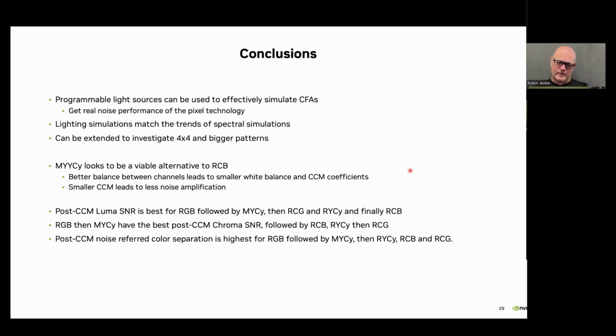I've estimated it as, if you have someone with dark clothing at night, only illuminated with a headlamp at the edge of its distance, maybe one lux, and then you go all the way through to something like the sun, and I'll justify that in a second, you've got something like 29 bits, maximum scene dynamic range. And we try to do our best.